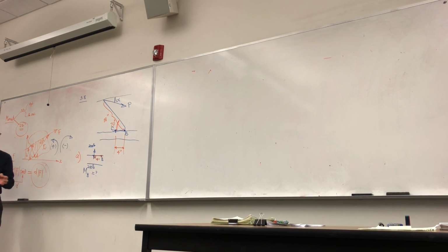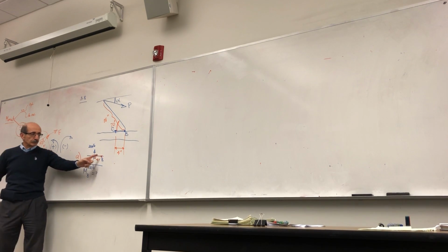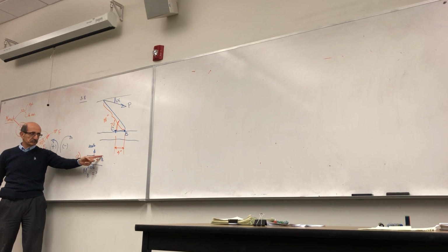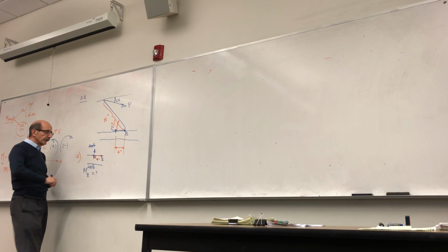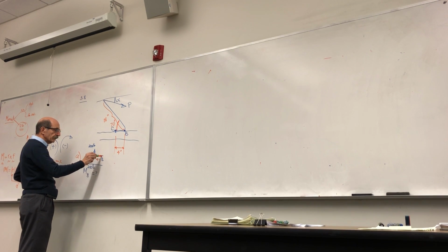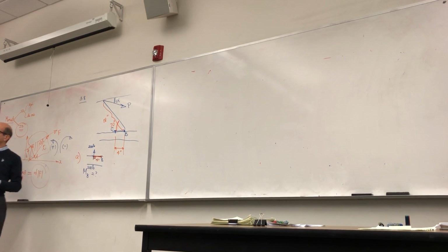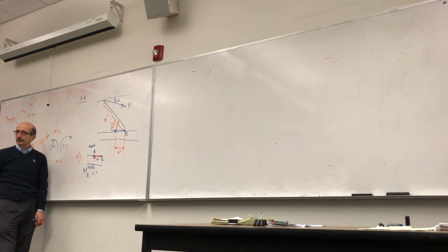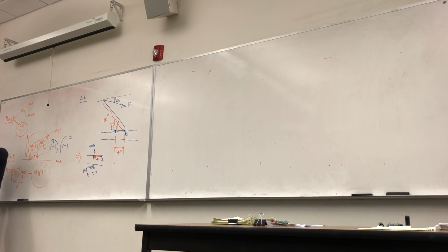The easiest way to find the direction of the moment, always think of it this way: you have connected that point to anywhere along the line of action of this force, versus this line, and assume that this is a rigid link, pinned here, and you want to move your force along the direction that is applied. What direction will this linkage rotate? Obviously that way, right? That is the direction of the moment that is generated.